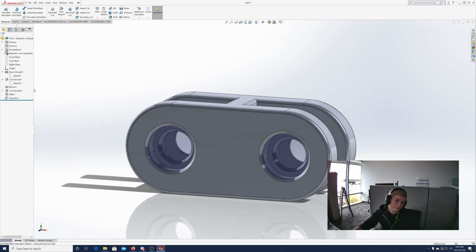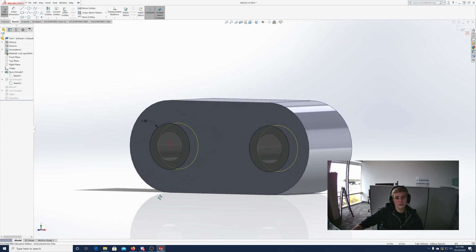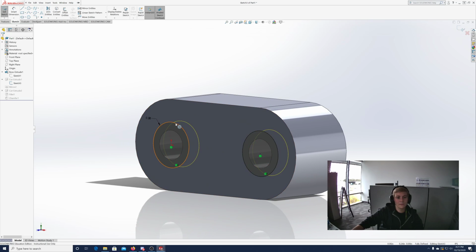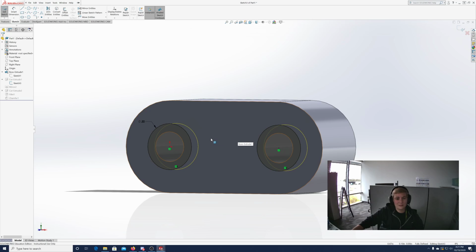I mean, it will affect other things, but if you're doing it correctly, like I just did that, I just edited that sketch 3 because I realized I didn't ever dimension my circles for the counterbore. So if you click edit sketch, it'll show you that sketch. So my sketch 3 here is those two circles, and I can change those now. I'm in that sketch. I can add something to that sketch if I want to.